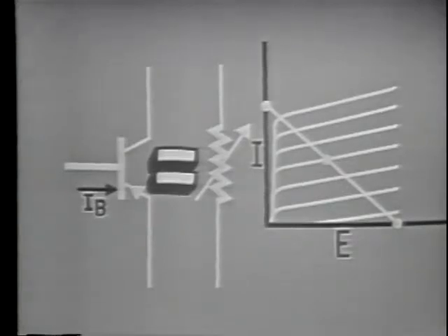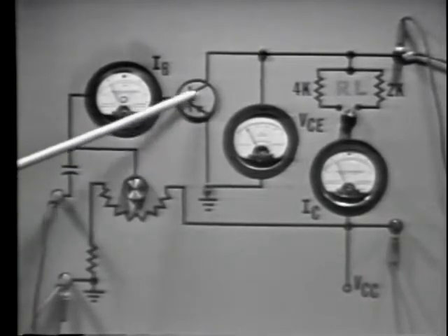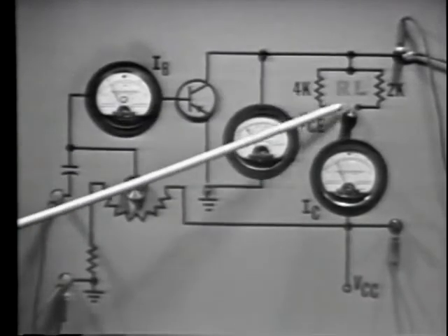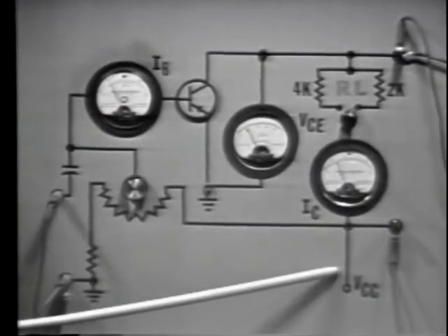Since a transistor acts like a variable resistor, we can use the idea of a variable resistance to describe the basic load line in a transistor circuit. Depending on the amount of base current, a transistor can vary from almost a short to practically an open. With this in mind, let's connect a transistor in series with a resistor known as a collector load resistor, or RL, and a power source, VCC.